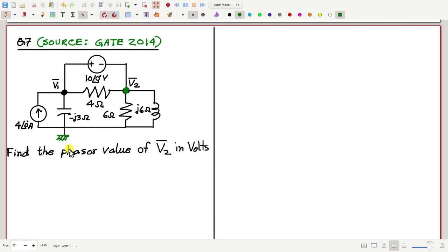So we'll turn that left side part into a Thevenin equivalent and then simplify it, sir. Or you can do it and then... The 4 ohm will be removed, I guess. You can do it, but I think we can remove the 4 ohm here because we can short it, as the 10 volt source is already connected. Yes. One very good observation.